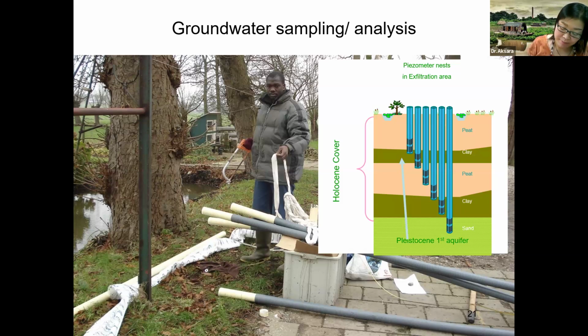Okay, so remember that I said we seem to have a three aquifer system: 1, 2, and 3. Well number 1 actually enters into aquifer 1, so the piezometric head that you read from well number 1 could be somewhere here. Well number 6 takes samples from aquifer 3, which is a confined aquifer, so you probably have a higher equipotential head.